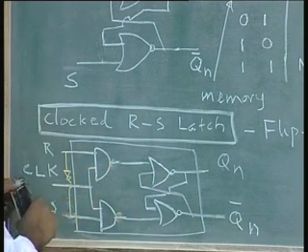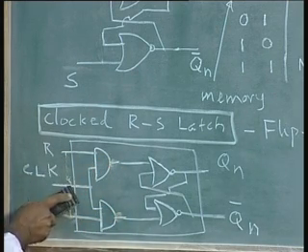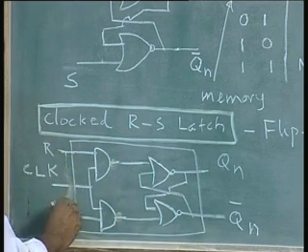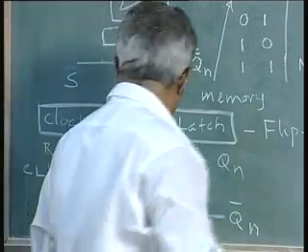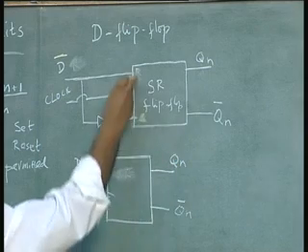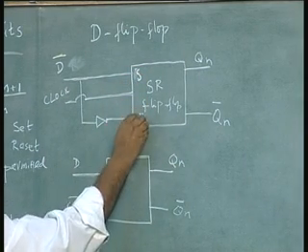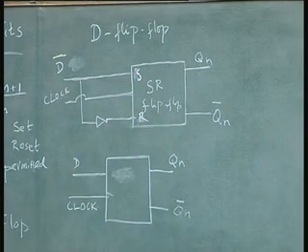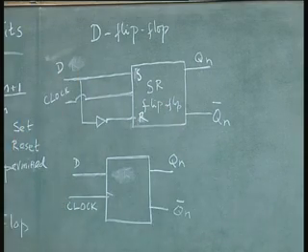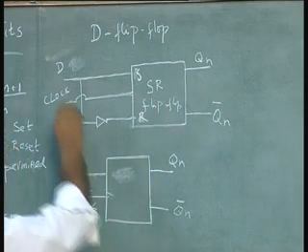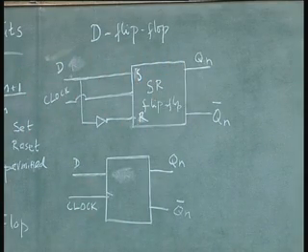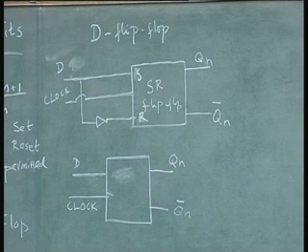I am going to leave this circuit alone where you had it in your notes. I am going to make the change here. I am going to call this S, I am going to call this R, which means when D is 1, Q is 1, when D is 0, Q is 0. That will be more like data storing. A 0 is stored, or a 1 is stored.